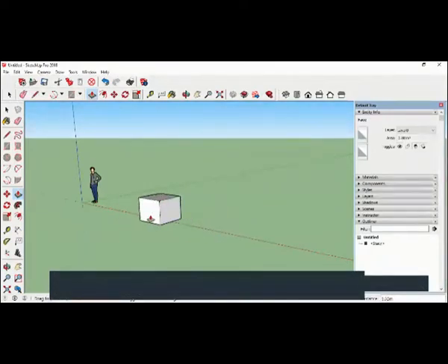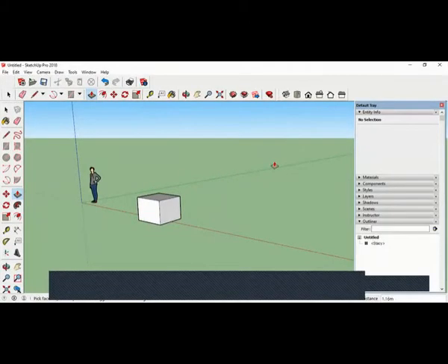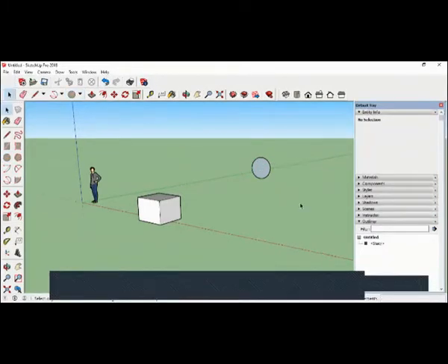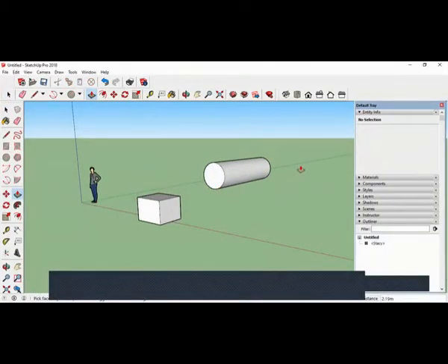Okay. Same way, suppose you want to draw an object perpendicular to this. So I will use the left arrow key now. Let me draw a circle, C for circle. Now I will press the left arrow key, and you can see that it is drawn perpendicular to this axis. Cancel it. And if you use the push-pull, you can see that it is extruding parallel to the green.